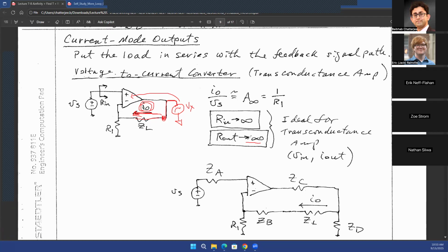Questions? When we do input impedance, typically we've had a test voltage source, and we check the current going through it, and then you use Ohm's law to get the input impedance. But here we add the voltage source, and then we're looking at the resistor. In general, can we add the test source anywhere and then just observe the thing that we care about, but we put it here because it was easiest?